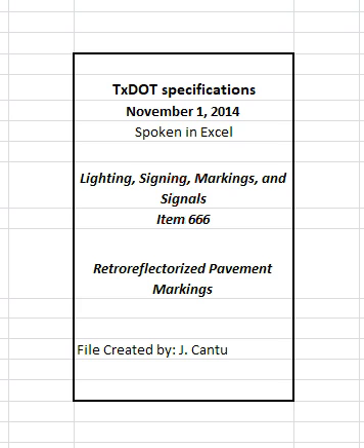4.4 Retroreflectivity requirements. When specified on the plans, Type 1 markings must meet the following minimum retroreflectivity values for edge line markings, center line or no passing barrier line, and lane lines when measured any time after 3 days, but not later than 10 days after application.